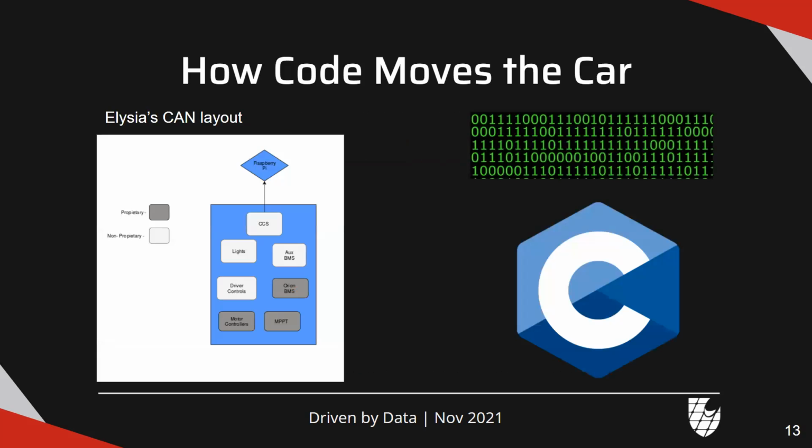So yeah, as you may remember earlier, I was talking about a communications protocol called the CAN message, and that just stands for Controller Area Network. CAN is basically a set of rules for transmitting and receiving messages. The electrical boards can send CAN messages to each other, and they are transmitted on something called the CAN bus. To put it in simpler terms, you can think of a bus as a set of wires that you can use to transport data.